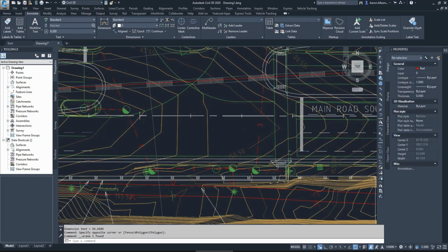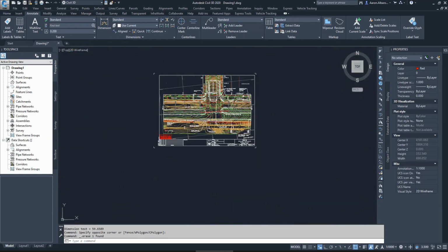Now, not all the time you've got these plans in PDF. This is very important, guys. This will be your step number one for almost lots of work that you have to do, especially if you don't have CAD layouts. In lots of our designs, we share PDF layouts, okay? Not all the times you get the CAD layout. So this is a very important step to scale our drawings correctly. Not all the times we're working with PDFs too.